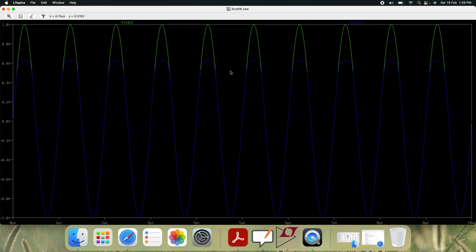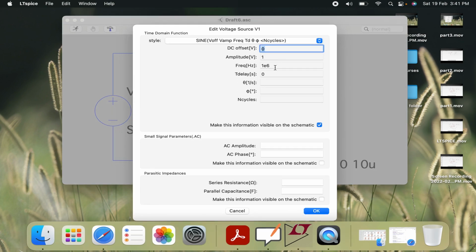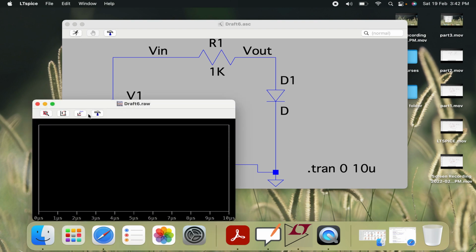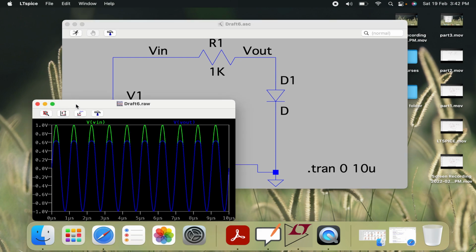Similar things you can do, and you can simulate it, and you can check the output as we have shown over here. And you can have all the possibilities, like in a sine wave also you can see that here the requirement of frequency is not like if you write mega in capital, it was creating a problem. However, you can give engineering scientific numbers also, like 1e6, then also it will simulate it and give you the required simulation, right, like this and as follows. You can see it gives the expected output.